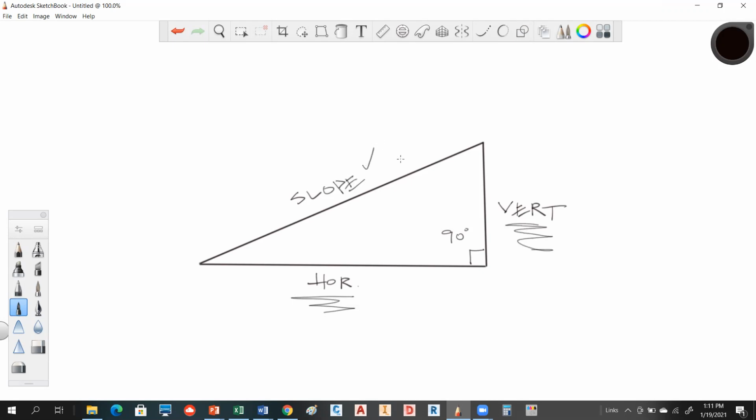If you measure the slope distance, you can convert that slope to a horizontal, or you can convert it to a vertical. If you measure this angle here, by measuring that angle, I can take that slope and convert it to a horizontal, or I can convert it to a vertical. That can be more convenient sometimes than doing that one or that one. But primarily, these are the kind we're looking at, the horizontal and the vertical. That's what your sets of plans primarily tell you.